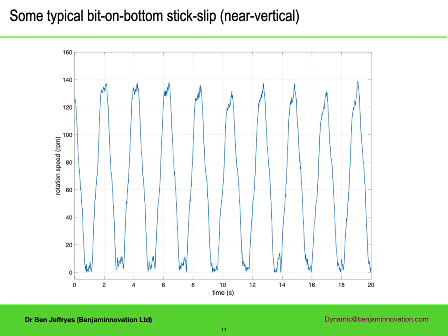You may think that somehow the bit stopping is driving this behaviour, except, while this example is for rotary drilling, you will see this just as much during motor drilling, with the motor rotating nicely at near constant speed. The drill bit is rotating at the sum of the drill string rotation speed and the motor rotation speed. So the drill bit is always rotating at a good speed, but the drill string speed is oscillating between 0 and twice the mean.